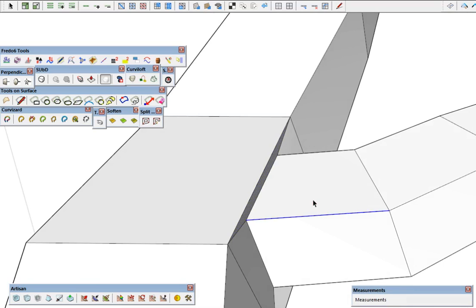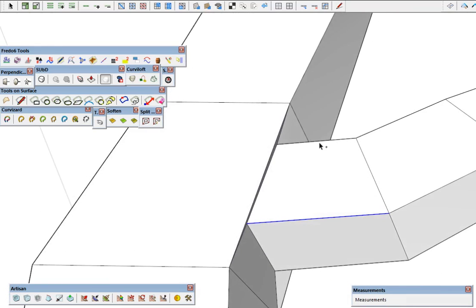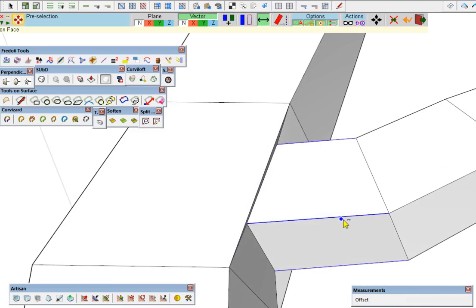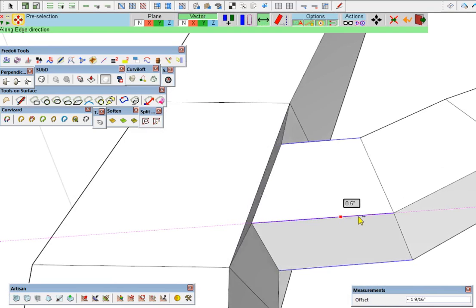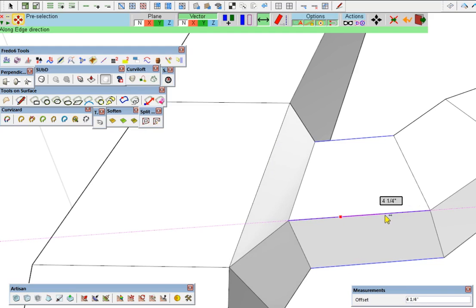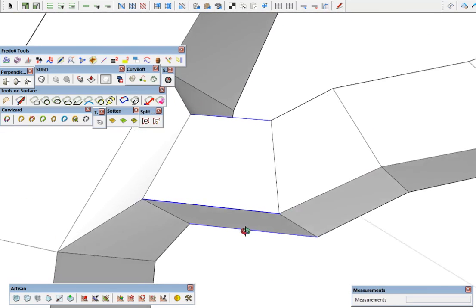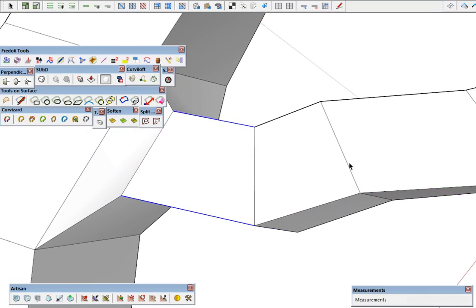And I'm going to grab this ring here, and we're going to move that along that direction there using move along. And I can't speak highly enough of move along and draw along, and I don't think they are as used as they should be, and I don't think they quite caught on just because they're such an embedded native tool.